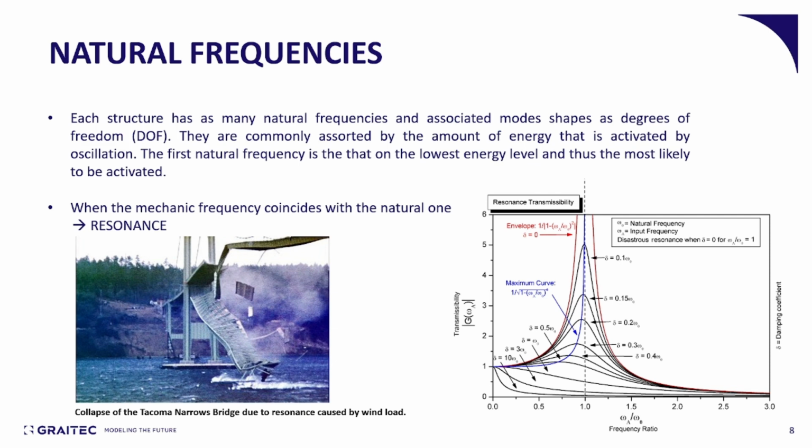So the whole idea behind the modal analysis, apart from the use in seismic design, is also to know the natural frequencies of the structure and check for any resonance effects caused by either the seismic load, which is a dynamic load, but also any other dynamic load, for example, the wind, any machine vibrations, anything that can act in a dynamic effect in the structure.